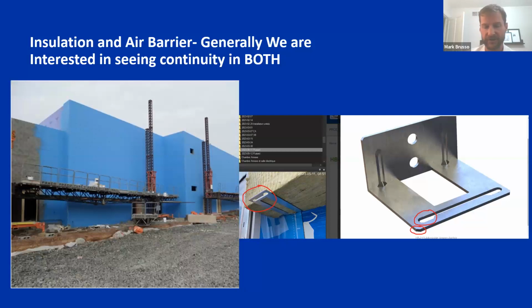On the right is an example of one of our masonry connectors, our 213, and I took a shot of a recent project I finished in Quebec. And another trend we're seeing with these deeper cavities and deeper insulation layers is the anchors are now growing. 4, 5, 6 inches of insulation is now the norm, where 10, 15, 20 years ago, it was 2 inches. And now we're seeing things even growing much further than that.